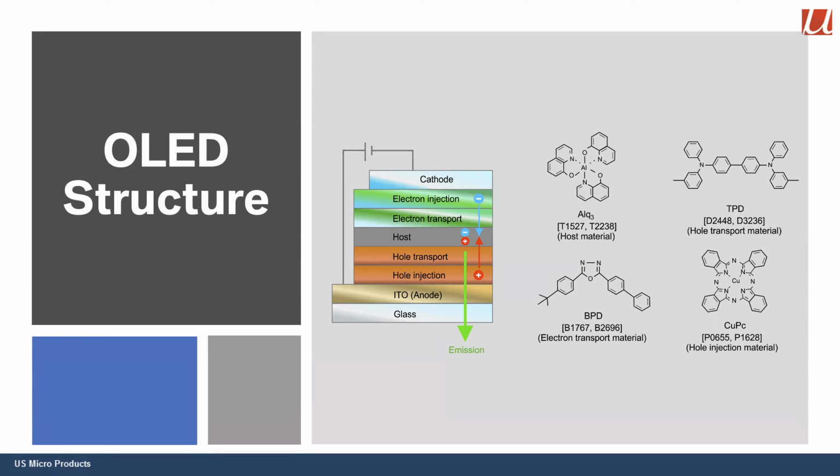So we've built a diode structure. It happens to be built of organic materials rather than semiconductors, but it operates the same way. Electrons are attracted to the holes, and when they come together, the electron pops back into the hole inside the host material, and that has the right band gap to emit the chosen color of light. And that light goes down through those transparent layers, including the anode, out through the glass, and gives you a display on the outside. So pretty complex chemicals, but it ends up being a very nice, color tunable light source.